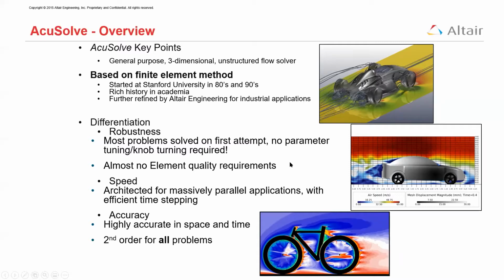You don't have to worry too much about capturing every little feature of your model, but you still need to make sure that you have some level of quality to your mesh. You don't want a 3 millimeter element right next to an element that's only 1/10 of a millimeter. That's where you get some numerical instability and likely some convergence issues. So make sure that you've got a decent level of quality, but don't worry too much about spending hours fixing it in every little corner.